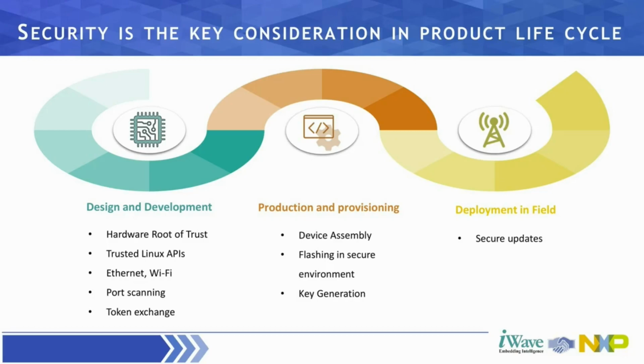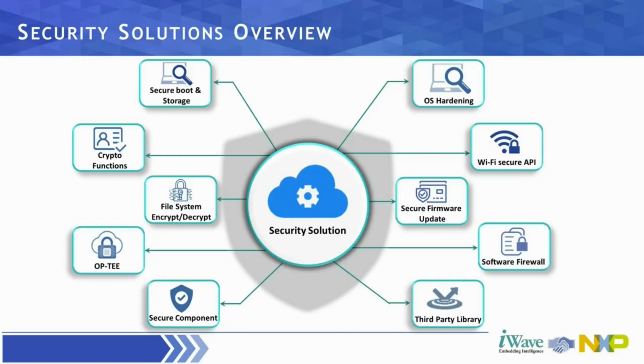Now going a bit deeper into the key security features. Let me give you a big overview of the features available. Silvano did touch upon a few of these functions available on the i.MX SoC, but maybe I'll give a bit more detail on how the process takes place. Secure boot helps the device resist attacks and infection from malware. It ensures that the boot technology and the operating system are the legitimate manufacturer version and have not been altered by any hacker. Next comes the crypto function.